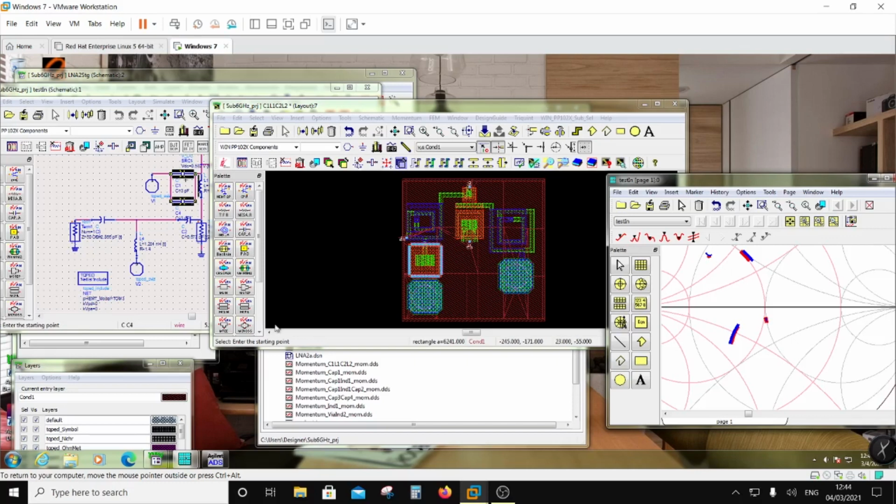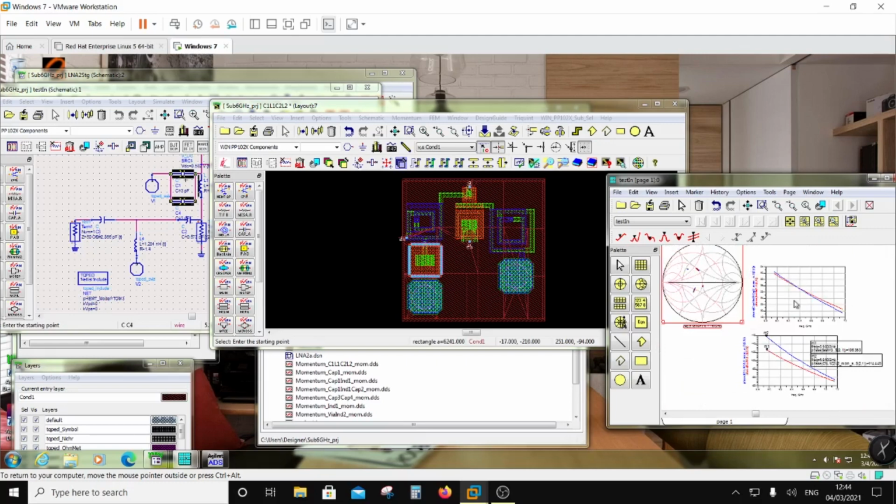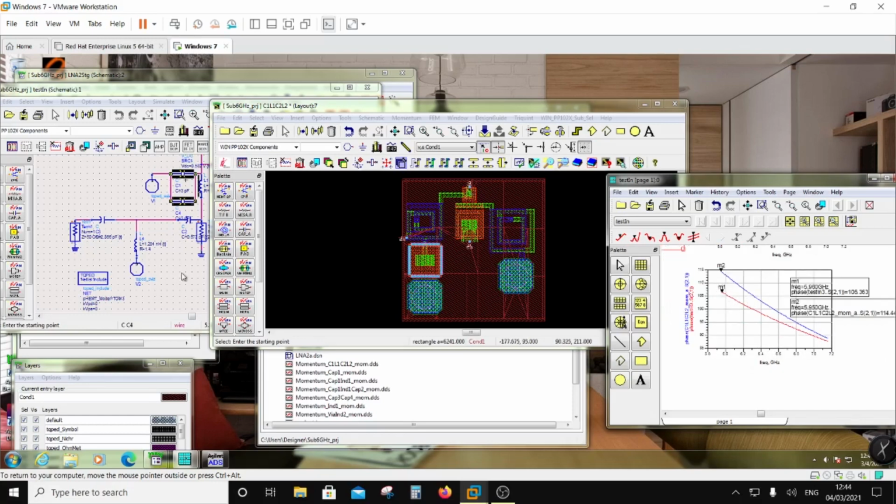So notice here, when I proceed from the input side up to the transistor, I keep an eye on S21, right? Everywhere I keep an eye on S21 and maintain it within 2 to 5 degrees. So when I finally reach here, the S21 phase differs across frequency. At high frequency, there is around 1 degree variation between EM and circuit, while at low frequency it is a large variation of around 8 degrees. Now this large variation of 8 degrees I'm not bothered about.